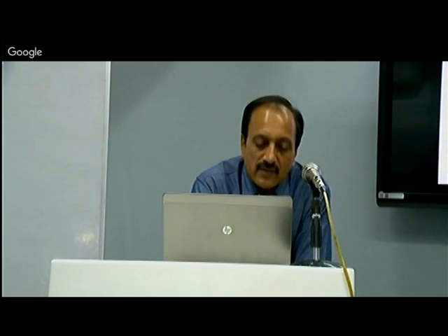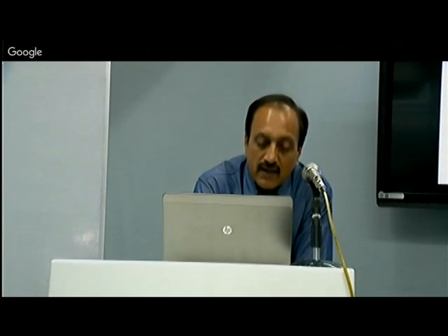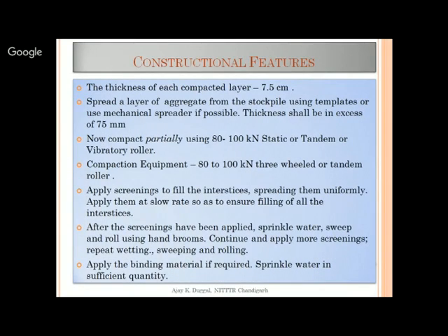जितने भी एग्रीगेट्स हैं उसमें सिलिका कार्बोनेट वगैरह प्रेजेंट होते हैं, उनकी जो नेचुरल कंपोजिशन है उसमें सिलिका एंड कार्बोनेट है. And if you know the composition of cement, सीमेंट में भी सिलिका और कार्बोनेट प्रेजेंट है. So the powder of the aggregate itself will act partly as a cementing agent. It may not be very high strength, but it has got a small to moderate strength, so that will help in binding the aggregate together. So that is why we suggest that you just sprinkle small quantities of water, क्योंकि small quantities होगी तभी पेस्ट बनेगा. ज़्यादा होने से वो slurry टाइप बन जाएगा जिसका कि बाइंडिंग इफेक्ट नहीं आएगा.